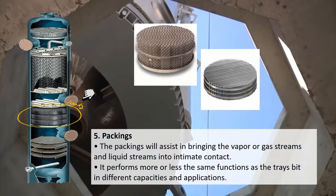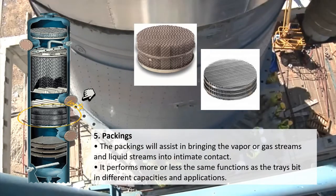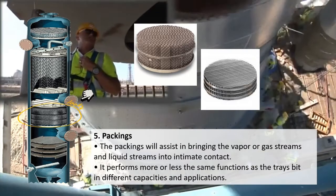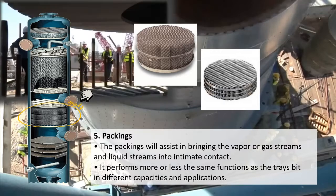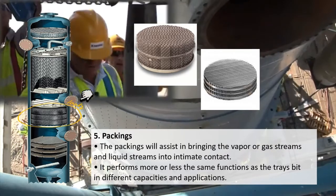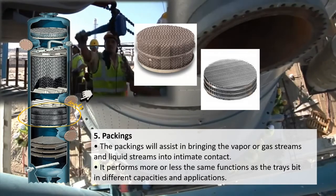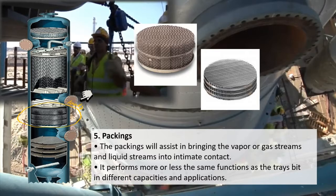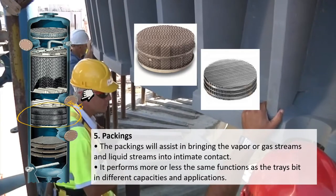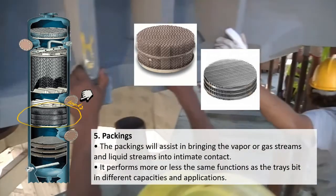And the last is packings. Packing is a range of materials that are specially designed for use in distillation and absorption columns, as well as chemical reactors. They usually consist of thin corrugated metal plates or gauzes designed to force fluids along complicated paths throughout the column. The packings assist in bringing the vapor or gas streams and liquid streams into intimate contact. They perform more or less the same functions as the trays, but in different capacities and applications.